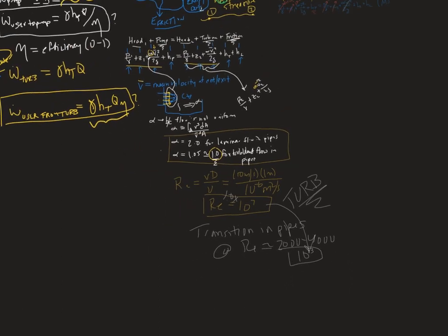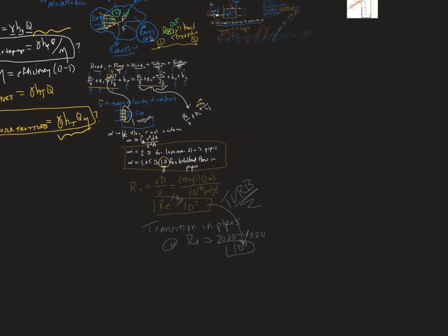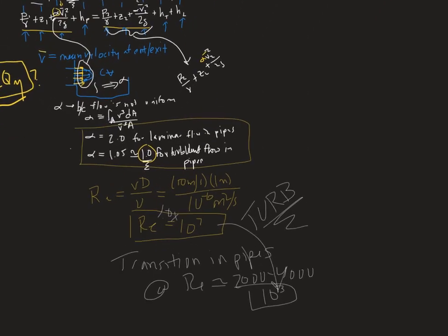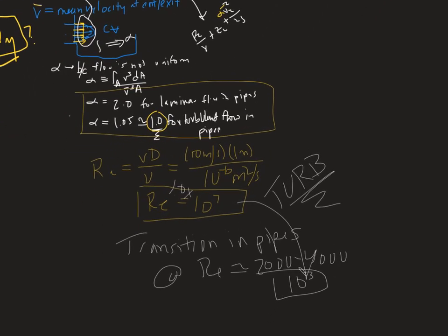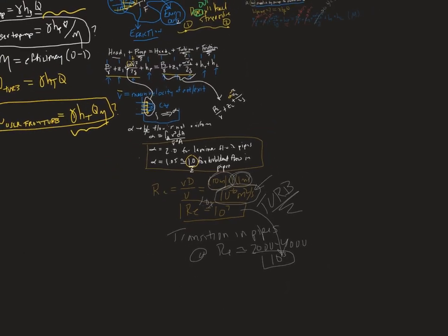So it's turbulent. I think you should be able to see that it's usually going to be turbulent because the viscosity is so small, and it's in the denominator. So in order for it not to be turbulent, either you need a different fluid, so the viscosity is different, or you need really small velocities or really small length scales. So think about that. You can actually plug some numbers in there and play with it if you want.